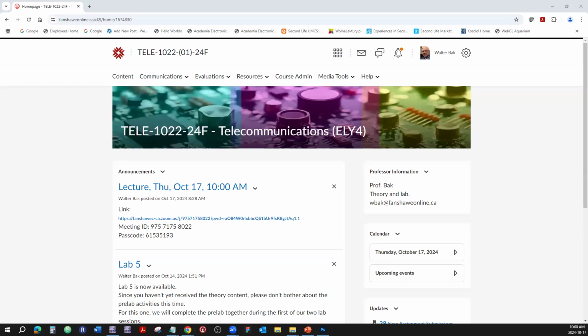No, it transmits through the Ethernet cable, but Ethernet cable in Cat5e is just using two pairs, one for transmit, one for receive. Now Cat6 and up, it's using two pairs for transmit and two pairs for receive. So still, if there are 24 or 48 channels being transmitted from the stage, well, you have to modulate it to transmit that over the two pairs and receive things over the two pairs. So things are being modulated. That's not an AM modulation, it's a different type of modulation.